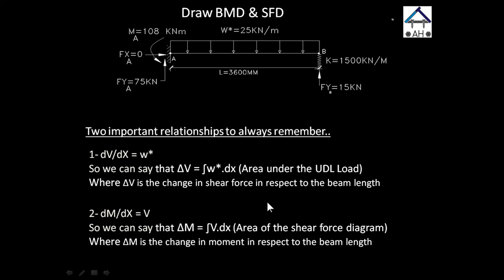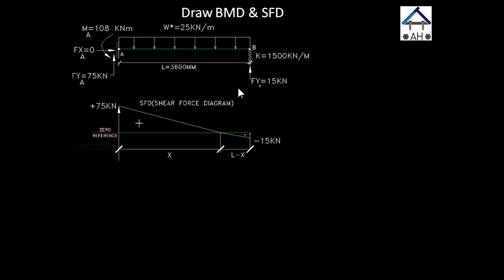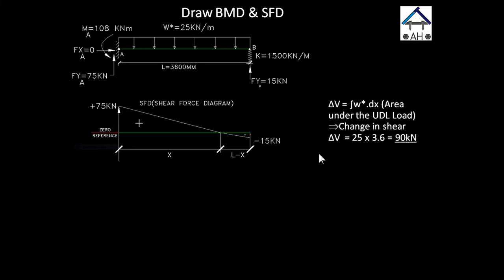Hopefully we can illustrate this more clearly in the drawing of the shear force and bending moment diagram in the next few slides. Okay, let's begin with the shear force diagram. Now we know that the change in shear is the area under the distributed load.